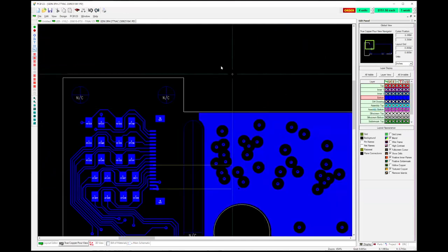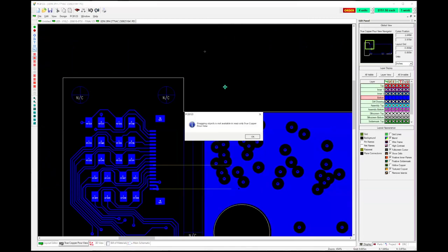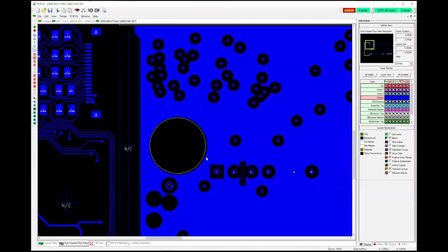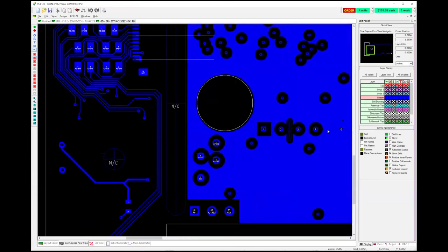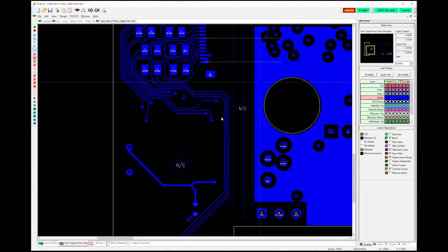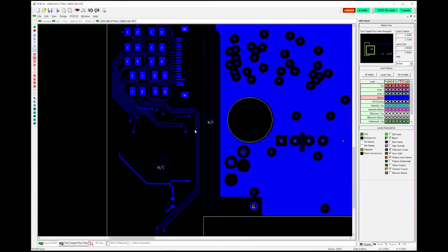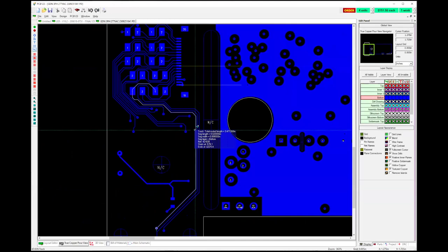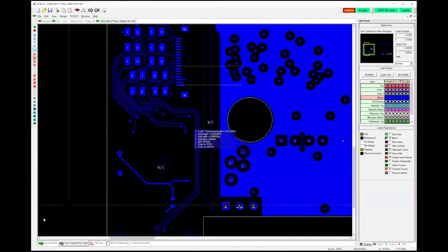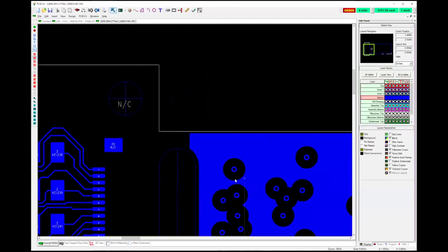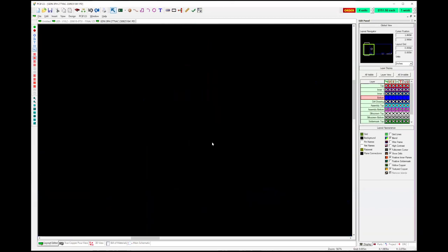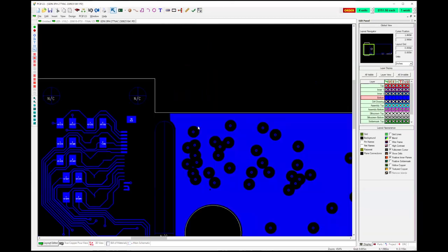This is exactly what the Gerber files are going to look like. So all the clearances are in there, all the places where the clearances overlap, because sometimes the board that you're looking at in the actual layout editor may have features that are slightly different when the Gerbers are drawn. It's just part of the tooling process, and this takes into account what's going to happen in the tooling process.